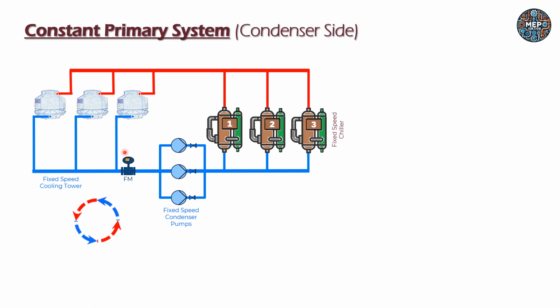In the condenser side, water keeps circulating in a fixed volume through the chillers with the help of this condenser water pump. Now, in this circuit, you see a pressure break here at the cooling tower, and that's the reason this circuit is called an open loop circuit, as there is a pressure break at this point, because water is coming to this point and the cooling tower nozzle is going to spray the water into the cooling tower and it is going to be collected at the basin.